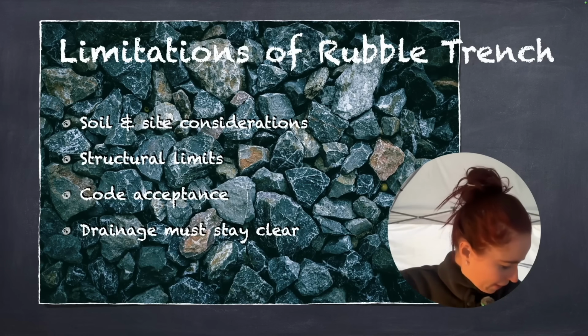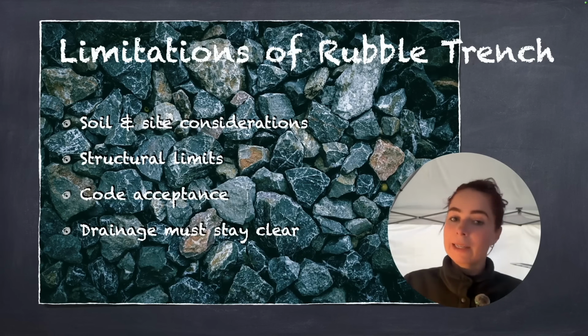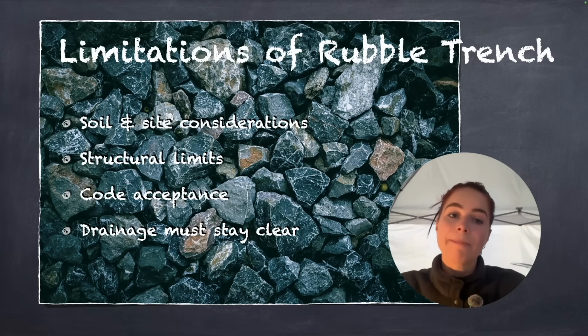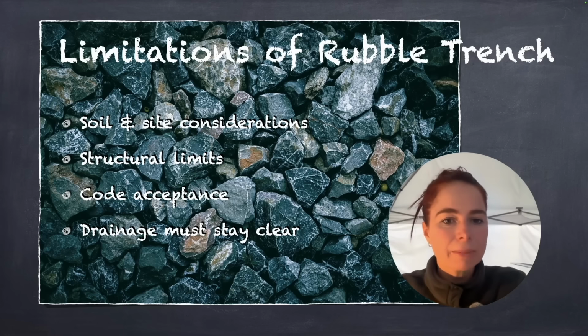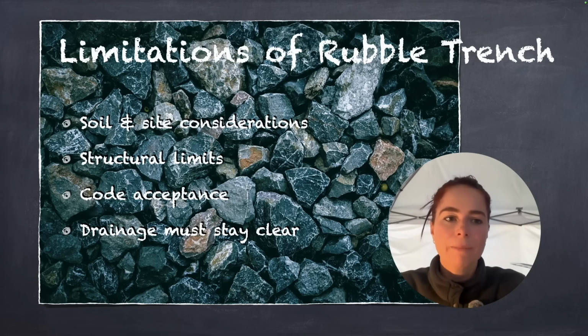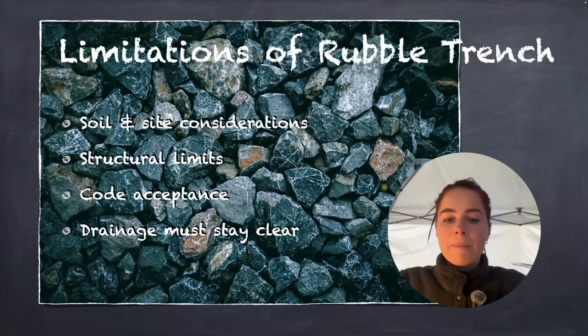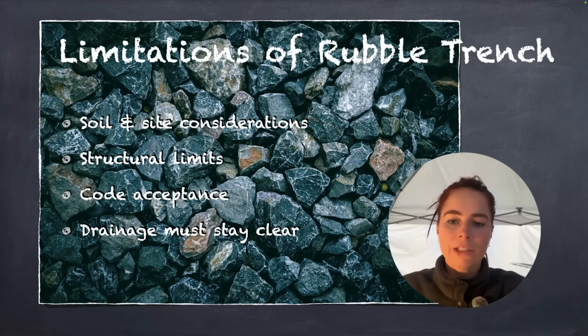So just continuing on a little bit about the limitations. There are some limitations of rubble trench foundations, so I wanted to talk about them. So one is you've got to consider the soil and site. It does work best in really well draining soils like gravel and loam. So if you do want to build with a rubble trench in a clay heavy soil, for example, they're going to rely on very excellent drainage design.